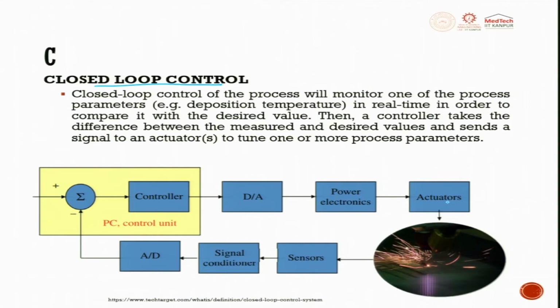So, whatever is getting actuated, a sensor is used to measure the actuator movement, and this gives us a signal. This signal is conditioned, converting analog to digital data, and then it is given to the summation, where a new signal comes and the old existing signal or set point is referred. The difference is calculated, and based upon the difference, the controller is moved again.